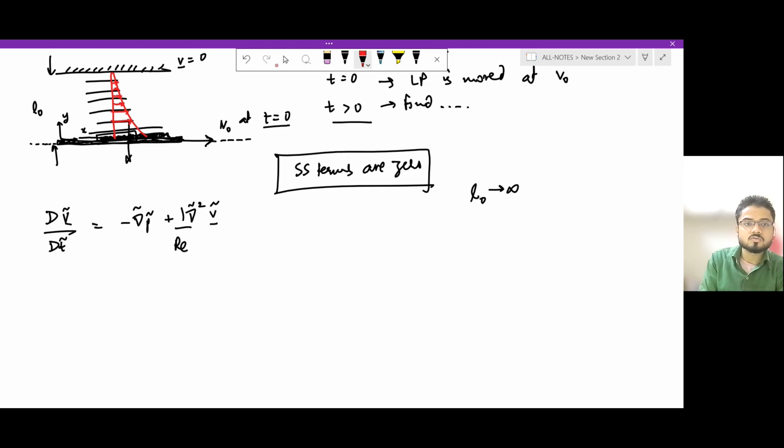So this is how the situation looks. Okay, so all of the previous layer is driving the successive layer. So this is basically shear driven flow. This is similar to the Couette flow part, but the difference is that in the Couette flow you had a finite domain of a certain thickness, maybe h, but here you have an infinite domain, and due to this domain being infinite, it would take